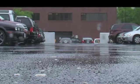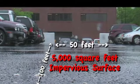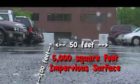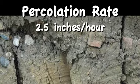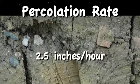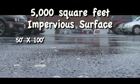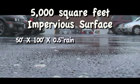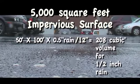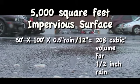For example, a proposed development project 100 feet by 50 feet has 5,000 square feet of imperviousness to be treated, and let's say that the proposed infiltration area was found to have a percolation rate of 2.5 inches per hour. First, the drainage area and volume required to treat is calculated. In this case, the area is 5,000 square feet, 50 feet by 100 feet, times half an inch of rain, divided by 12, because there are 12 inches in a foot, gives us 208.33 cubic feet of volume required to treat for the first half inch of the proposed development site.